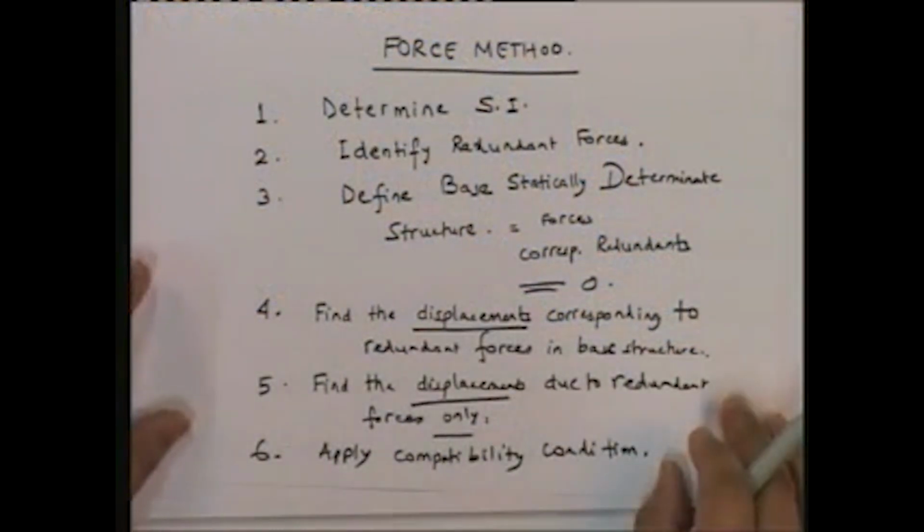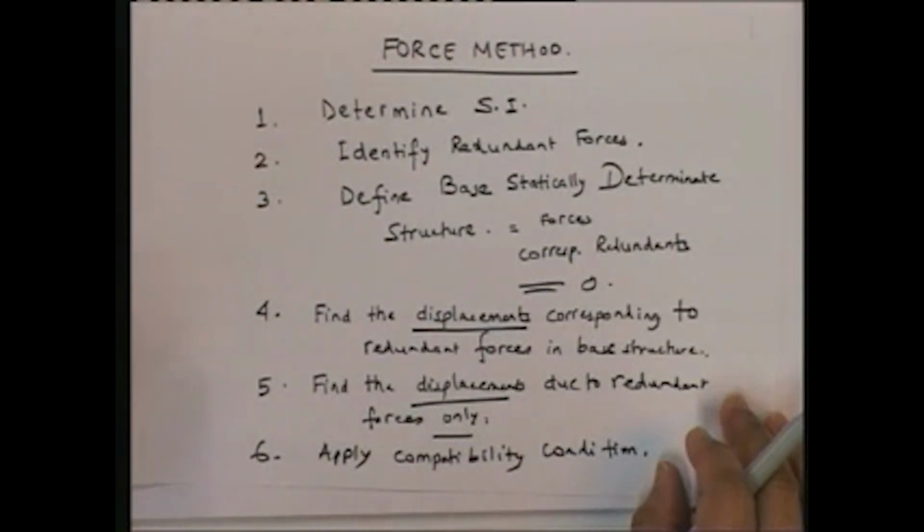Now in this lecture I am going to be applying the force method to a beam. And understand one thing, and that is that you have to be able to find out the displacements in the structural analysis that I am going to be doing. Remember, I said to find displacements I'll always use the virtual force method. So the whole process over here is based on the virtual work principle. Remember, I said that I was consistently going to use only virtual work, and that's why here, where do we use virtual work? We use virtual work to find out the displacements. So that is the overall concept that I'm going to be using over and over again.